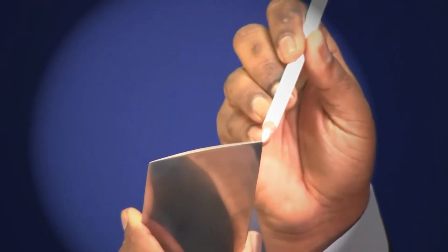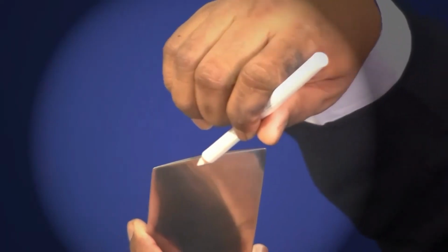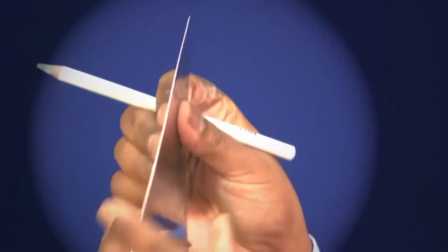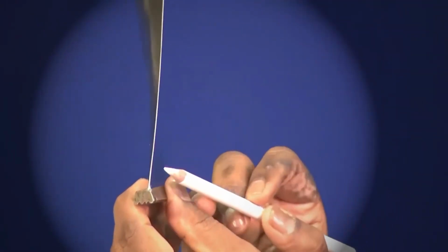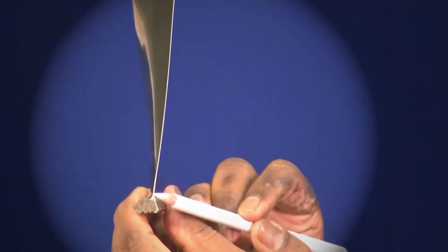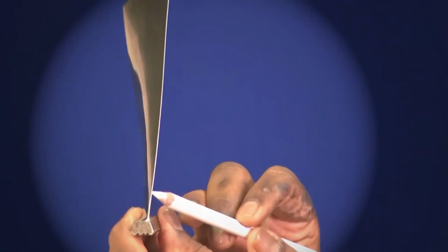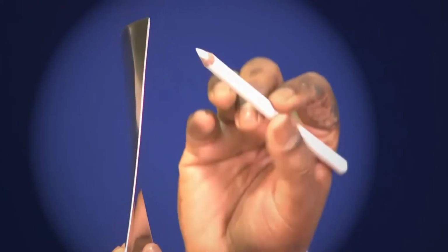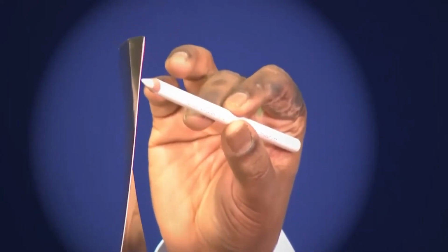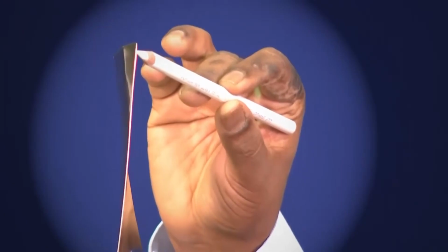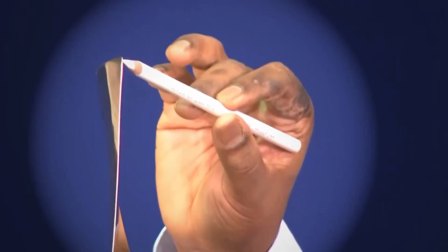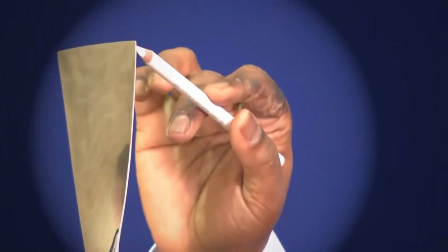So you can say this is my first circular arc, this is my second circular arc. And if you look carefully near the hub region, the blade shape is different, and the leading edge thickness is different. And if we move upward near the tip region, the leading edge is sharp, and the trailing edge also is sharp.